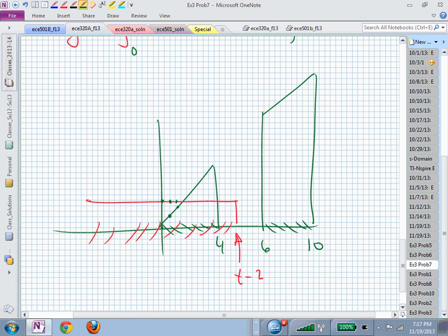Because your convolution is the product of x with h of t minus lambda, point for point, and that gives you maybe some weird function, but you now find the area underneath that function, and it might be a function of time. Yes? So using the area and the scaling in order to find the integral only works if it's constant.